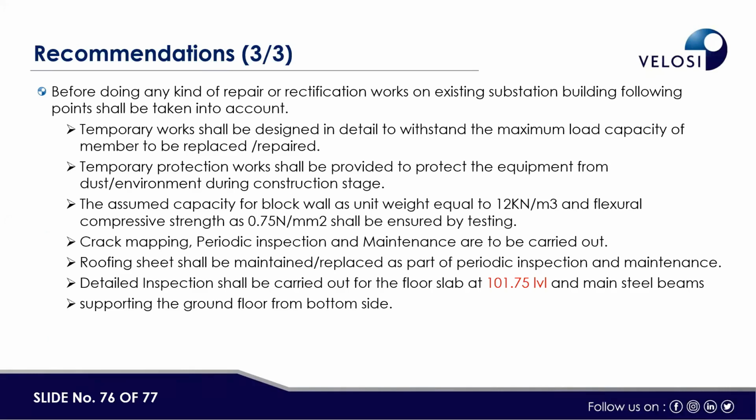Then the condition of the roofing sheet shall be checked properly. Detailed inspection shall be carried out on floor slabs supporting the ground, from the bottom side. If any temporary measures or inspections are to be done, they should be carried out with proper measures and temporary supports, so that the main structural components don't get damaged during this inspection or assessment. Periodic maintenance should be done so that no other damage-causing component gets into the reinforcement portion of the structure.